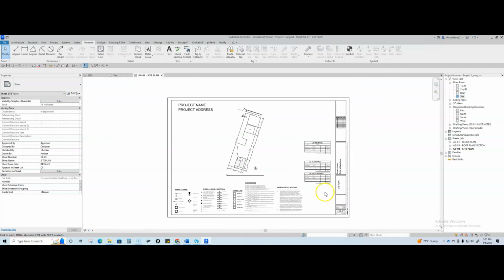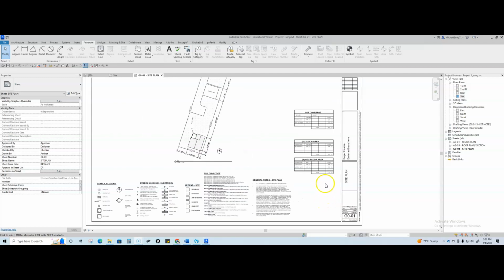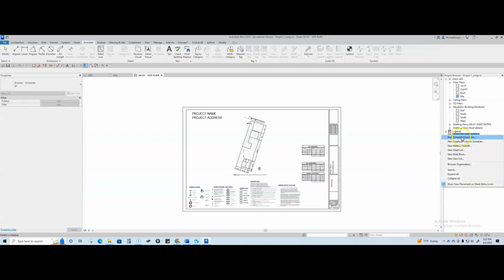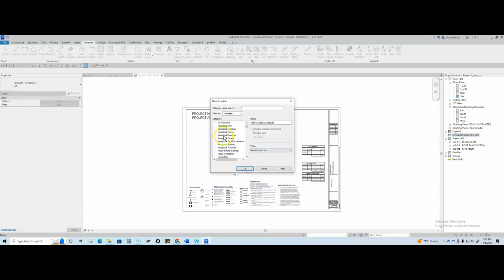And then let's talk, oh yeah, we should do this sheet schedule. So drawing sheet index usually goes on the cover sheet. We call this the cover sheet. And that's where we specify to the contractor, plan checker, whomever is going to read these plans, how many sheets are in this package and the name of each sheet, right? So to create a sheet schedule, you're going to come here and you're going to right click and you're going to say new schedule, and you're going to go to sheets.